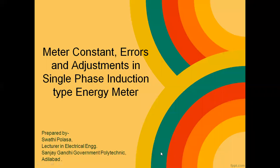Hello everyone. Welcome to the presentation on meter constant, errors and adjustments in single phase induction type energy meter. In this video lecture, we are going to see the meter constant and what are the nameplate details of a single phase induction type energy meter, and what are different types of errors we see and how to adjust the errors. How do we go for compensation of those errors?